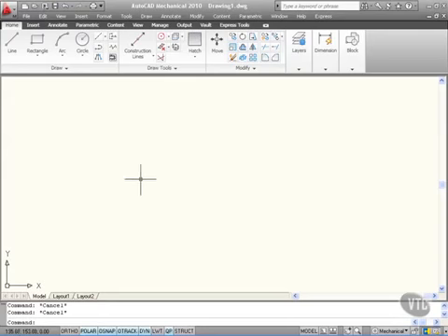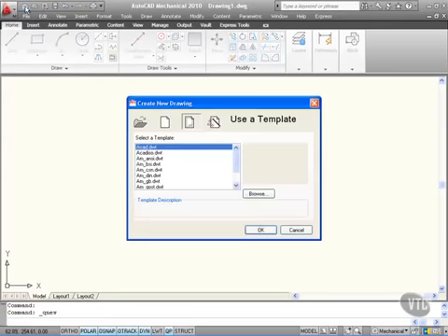So the basic concept of AutoCAD Mechanical is that you're going to draw something. But what you need is something that will allow you to draw something over and over again. That's where your templates come in. Now, if you remember previously, I got you to set up the startup variable. And you set it to 1 so that when you clicked on New up here on the Quick Access toolbar, you got the Startup dialog box.